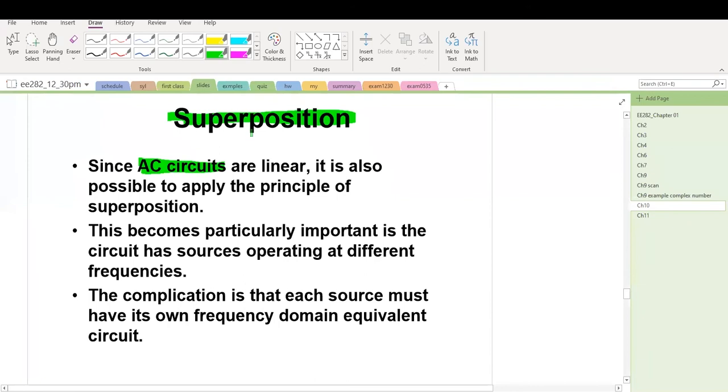The superposition theorem can also be applied in the phasor domain for AC circuits. The only catch is to pay attention to different frequencies on different sources. So for different frequencies, the impedance needs to be calculated again with regard to the frequency specified for that source.